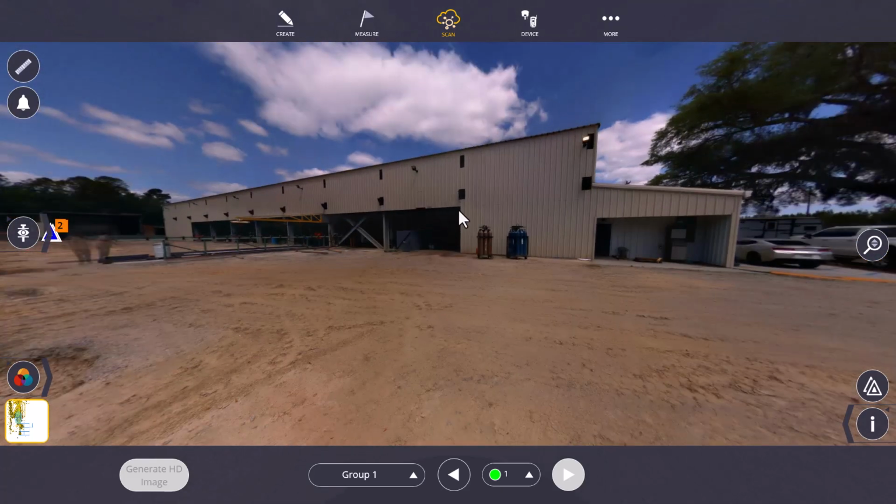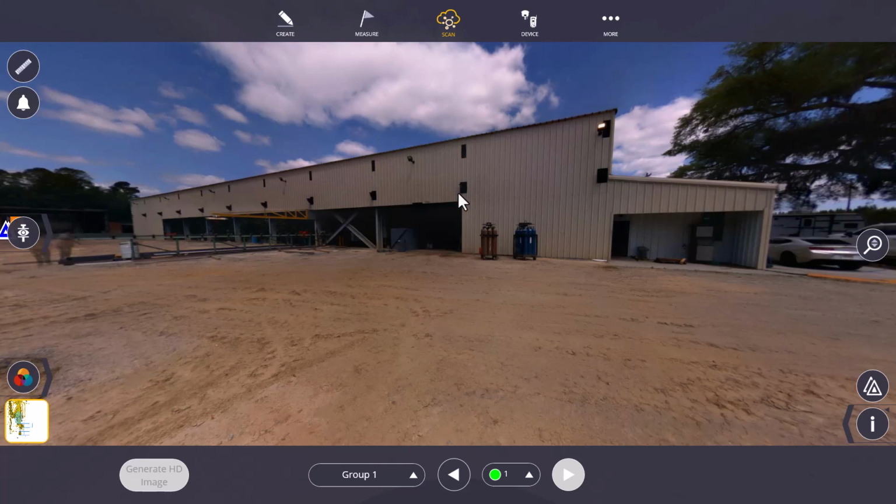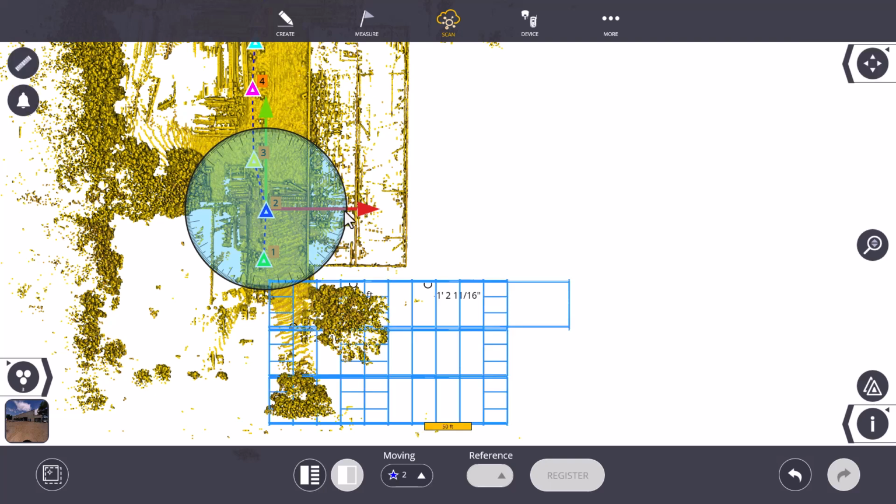We're going to QA/QC that these fittings are going to fit and were essentially installed correctly so that the steel that comes in after is going to fit. You could use the scanner and actually resection it and place it to control. In this example, we're going to show you just how to manually do it.